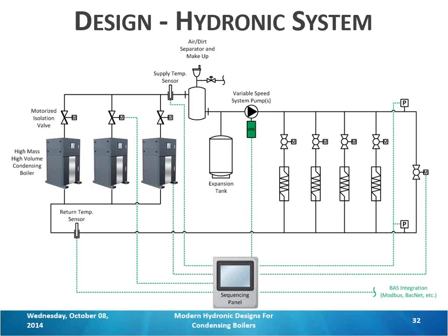You base this on a 30-degree delta T. Is that typical? I would say it is. Most systems are between 20 and 40-degree delta T. Usually you don't see much above 40 because most have air handling units and coils, and it's hard to get a selection above a 40-degree delta T. Unless you're in a process application or snow melt, radiant floor, usually you won't see above 40.